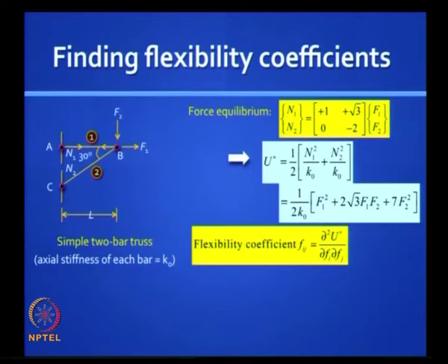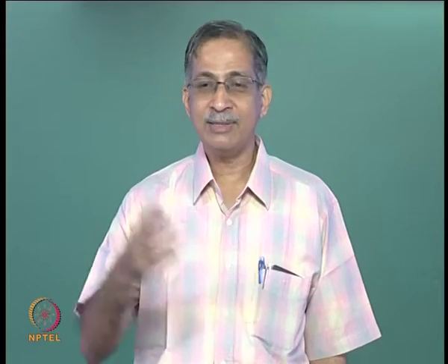Now you write an expression for complementary strain energy, and you must remember the Castigliano's theorem simplified everything, because it got rid of load potential energy, it got rid of total potential energy, and so you have only strain energy and complementary strain energy. Many students when they study structural analysis remember only that, but it is good to remember the background which includes the load potential energy term.